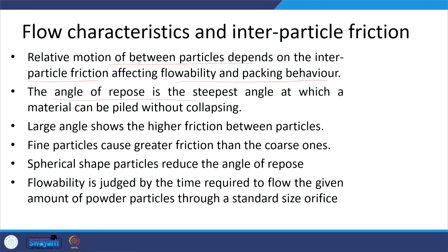Angle of repose, as I have said, is the steepest angle at which material can be piled without collapsing. Okay, so the higher the angle, the greater the interparticle friction. A large angle shows higher friction between the powder particles. Okay, fine particles cause greater friction than the coarse ones.